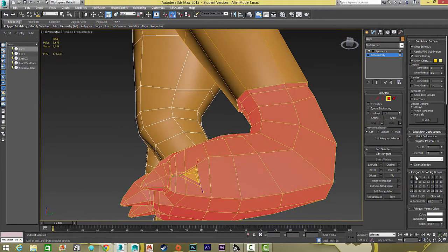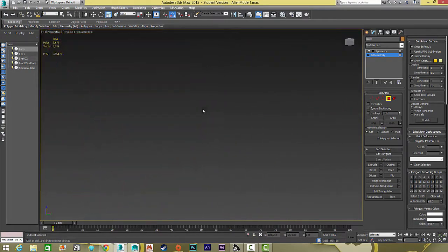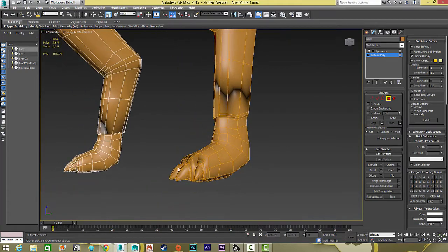Turn off smoothing group 1, turn on smoothing group 2, and then we're going to shrink one time to get off of that inside skin loop, or inside clothing loop. Turn off smoothing group 2, turn back on smoothing group 1. Now you see that smoothing issue's gone away. Back legs, same process. You can drastically see a smoothing problem there.